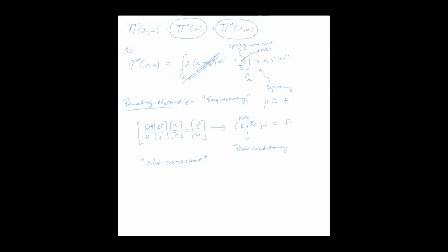So this penalty term, if you couple it with the Lagrange multiplier term, will not create the same conditioning problems, which is why it's often used in contact, because it provides some stability to that problem of conditioning. Okay, but we don't like it because we now have a mixed problem or a saddle point problem where we have these constraint matrices that are involved, and the solution procedures are more difficult now.